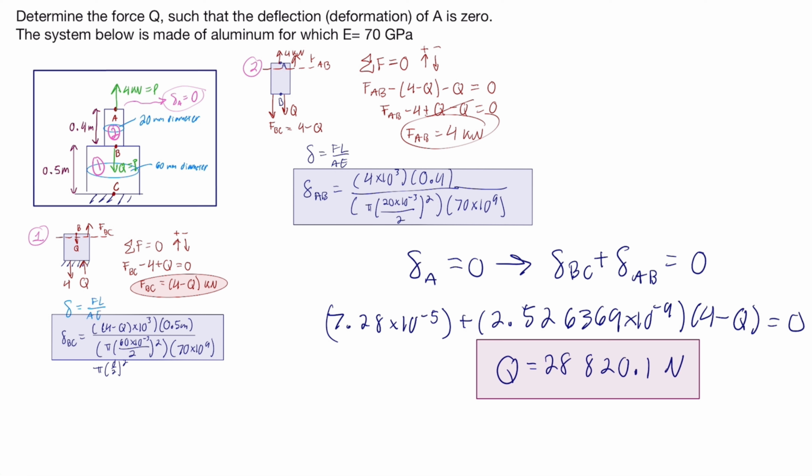So some steps to keep in mind when solving these types of problems is to first make sure that you divide the system into segments depending on if there is a change in area or if there is different forces applied at different points. So that's when you want to split it into segments.